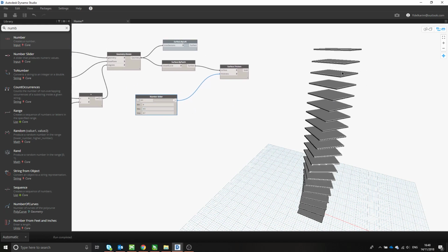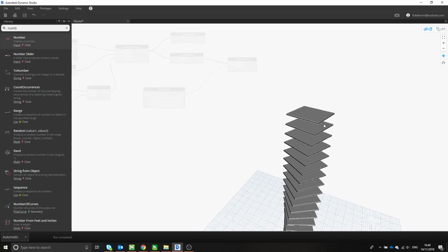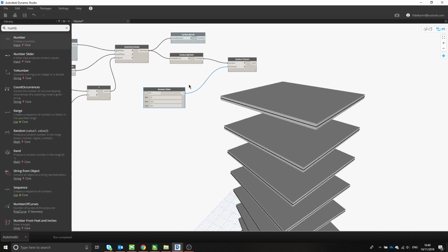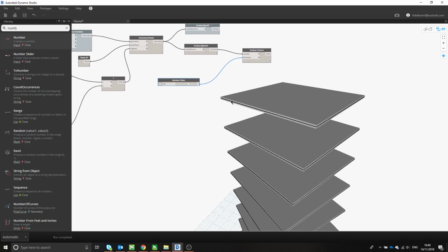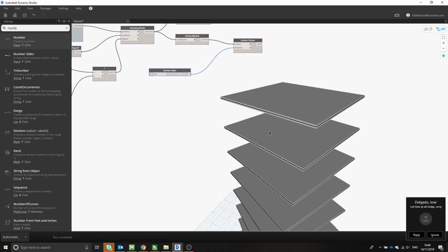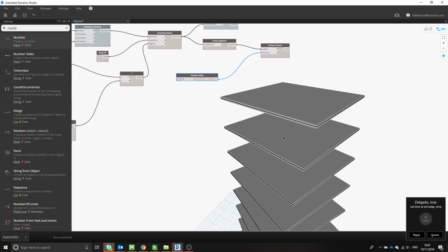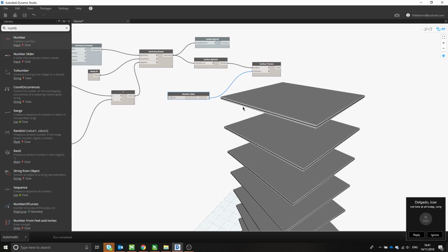Even that is pretty thick. And now you can change the step. Well, 0.1 is good. Make it thinner and thicker. But remember, it does it equally about the rectangle. So there is a way of thickening it downwards only or upwards. But we'll go through that in the future.